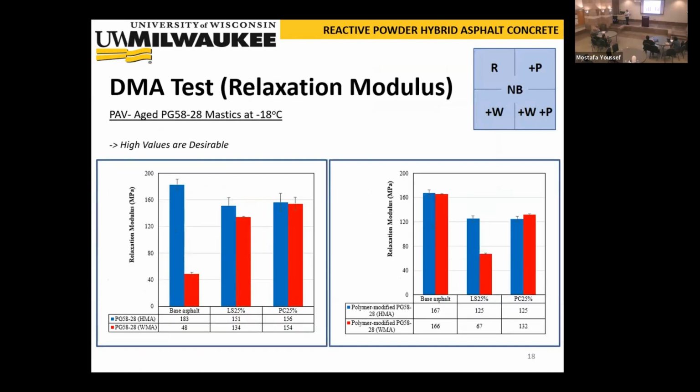Looking at the relaxation, we are seeing that the warm mix additive drops the relaxation of the binder significantly, which is counterintuitive if you didn't see the results. However, the binder recovers that ability to relax as the particulates increase. So that interaction or increased stiffness, or I don't really know what yet because we didn't look into it, seems to negate the bad effect of the warm mix.